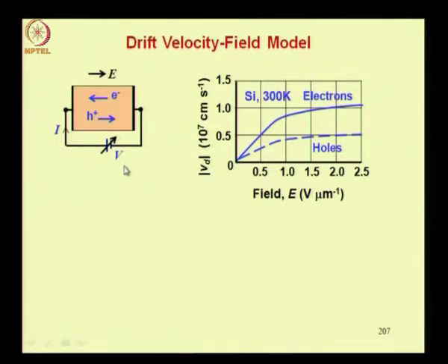This is very important, that we are not varying it rapidly. So the variation is so slow that corresponding to any voltage the conditions in the device can be regarded as steady state. This voltage sets up an electric field E that is causing the electrons to move from the right contact to left contact, but holes move from left to right.